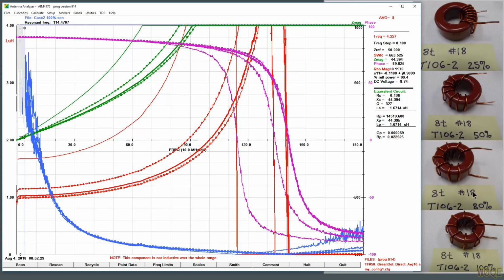But what we see here is a case where if we were to physically want to mount these, you mount it this way, you can bring the turns down this way. If you bring the turns down this way, you have to add the extra inductance for the wire. And if you bring them this way, the path is a little shorter to mount, but the turns sit against a piece of circuit board or however you're mounting them, which isn't optimal. This way is a pretty good mounting. This way is good mounting. This way is very bad to mount on a circuit board because you can roll this way or this way because these 2 turns are lined up. And this is not nearly as secure of a mounting.